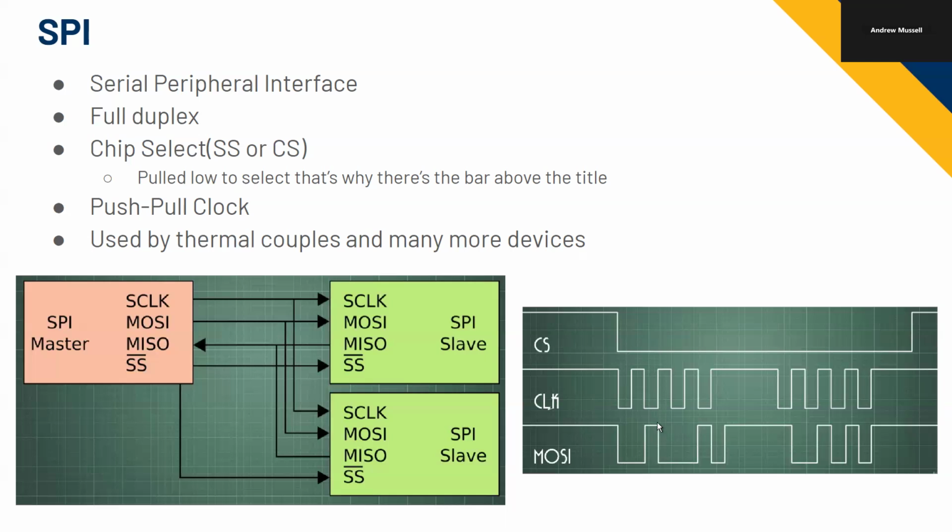You can see this rising edge lines up with this being high, and then it goes low to wait for the next rising edge. Up until that rising edge of the clock, you need setup time. So the data needs to be good and solid for some amount of time before the rising edge of the clock. And then you need hold time. Sometime after the rising edge of the clock, you need to keep it steady until the hold time is up.